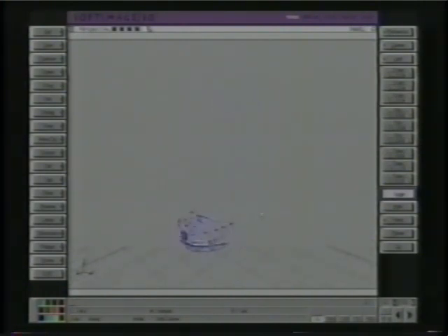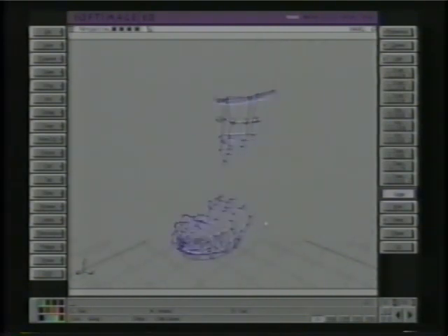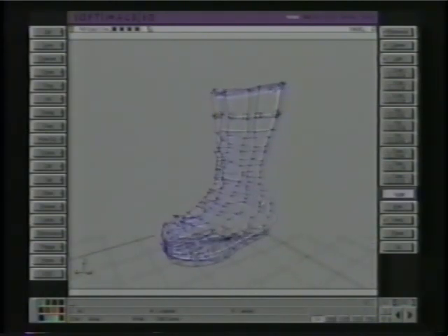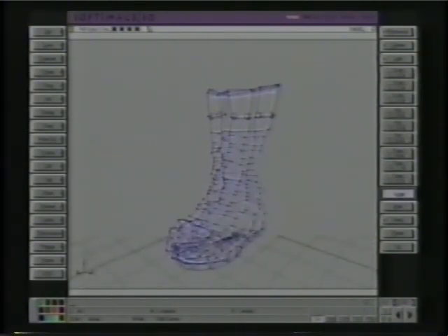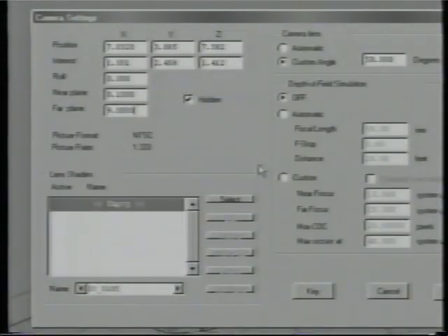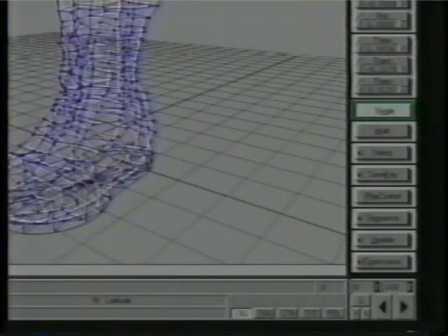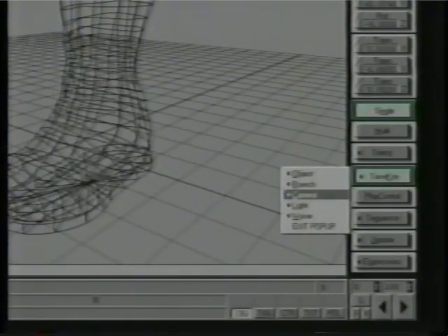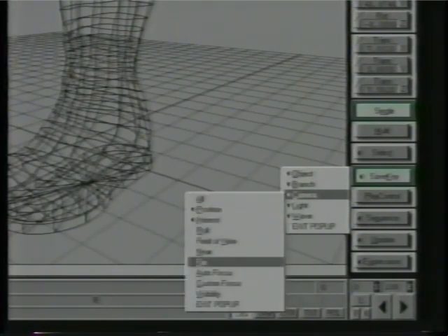And if you use the P key, you can scroll in and out of that. So this is really handy for seeing objects. Even nicer is if you set up a little virtual slider to make this happen. Set the camera far plane to something like 60. Select the camera and then save a camera keyframe. Save key, camera, far.